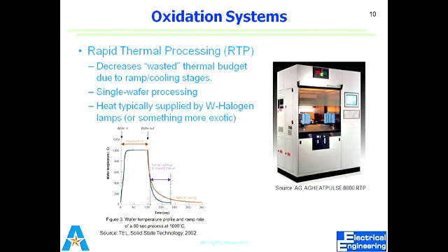Okay, we were talking about the rapid thermal processor, that is RTP. Before going to it, in the furnace we can use both wet oxygen and dry oxygen. Yes, in any furnace, it depends on what the ambient is, what the oxidant agent is. That's why I'm using the term oxidant instead of oxygen or steam. So we can use both. What we'll be using tomorrow in the lab would be dry oxide. So in dry oxidation, what would be the oxidant? That would be oxygen, not the steam or the water vapors.